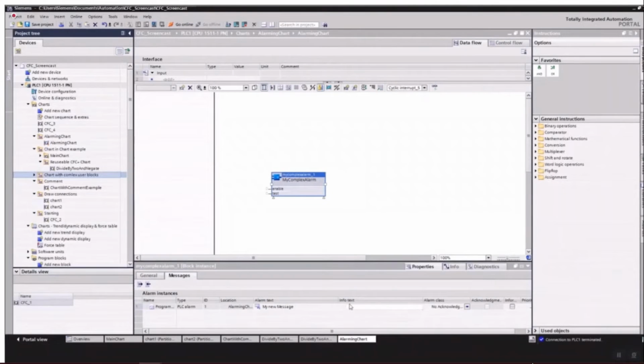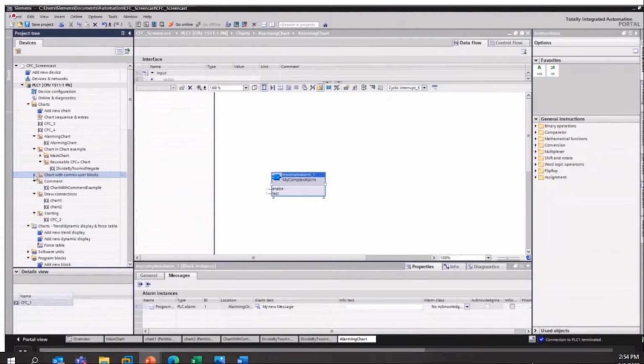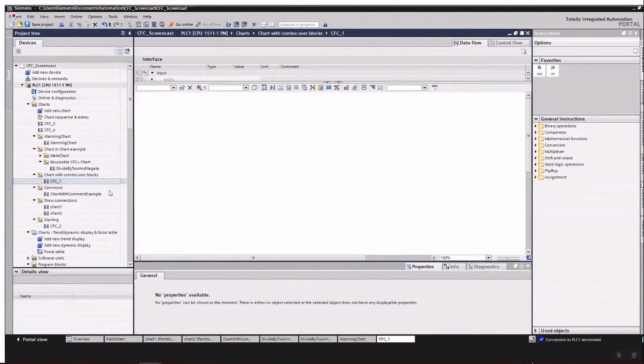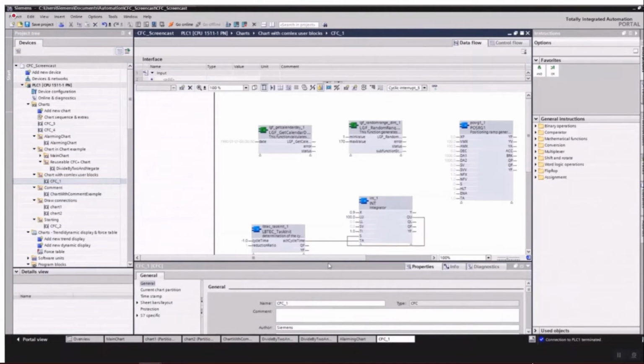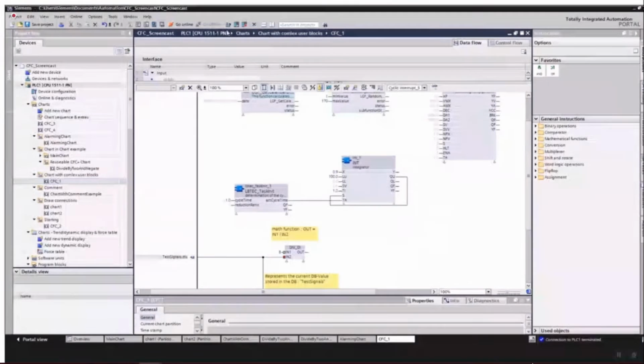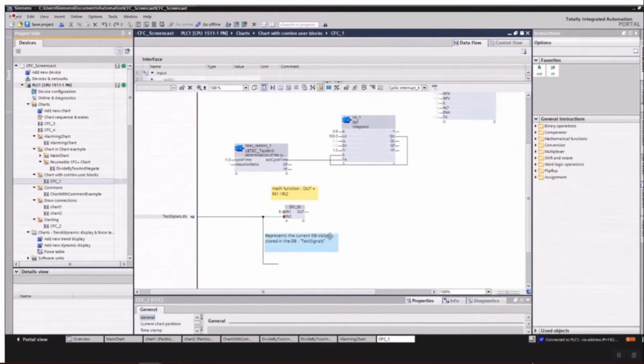As we have completed the user program, I will show you how the CFC looks when you go online on the controller. The initial download requires a complete software download that includes a PLC stub. Smaller changes can be downloaded while the PLC is still in run. I have already executed the initial download. I just have to go online.